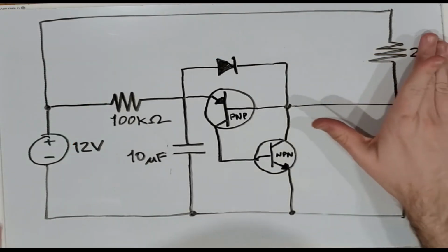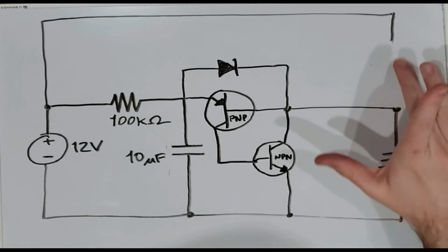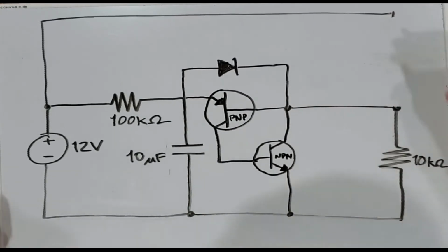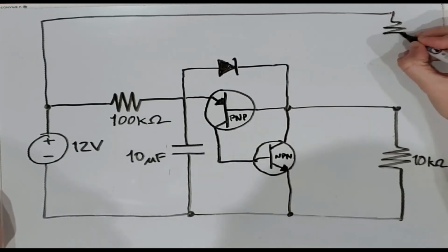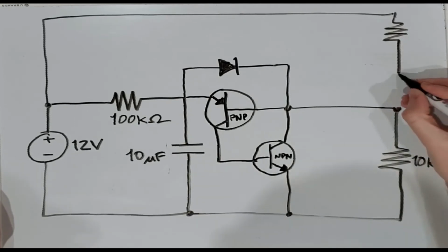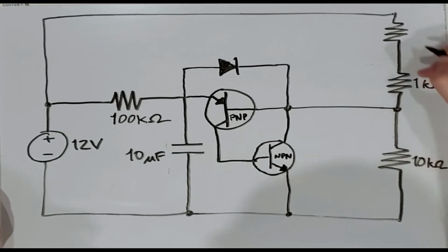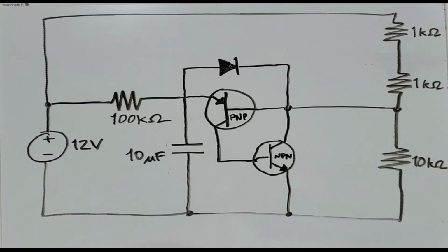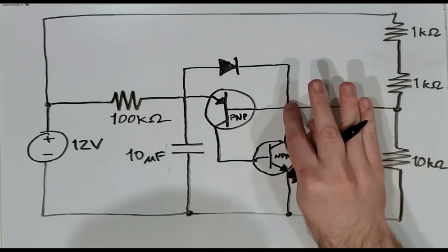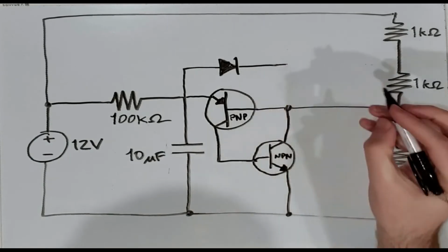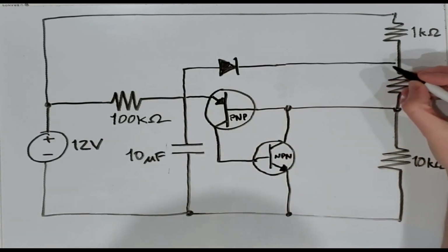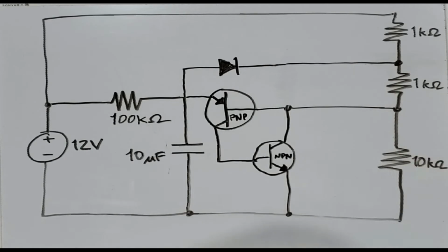I'm going to take our voltage divider and divide it even more. We're not going to change the threshold voltage that activates the PNP transistor, but we can raise the voltage that activates the diode. So by tying the diode to this upper node, which has a voltage of 11 volts, and tying the PNP base to this lower node, we ensure that current is going to start flowing through the PNP transistor before current starts to flow through the diode.